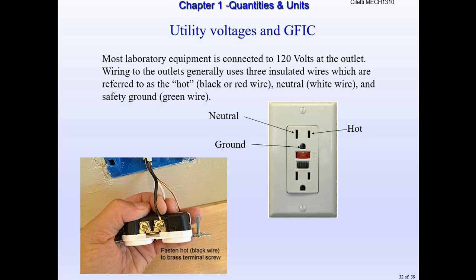But all of your outside circuits, so if you lose power, like maybe in your garage or your outside circuits, chances are the breaker didn't trip. Something happened to your GFI, and you have to go reset the GFI and not the circuit breaker in your panel. Same in your bathroom. So it's usually the first circuit in the series, and there'll be 3 or 4 more plugins on that. Your garage door might not be going up and down because the GFI that it's on got tripped, so you need to go reset it. Hit the red button there.